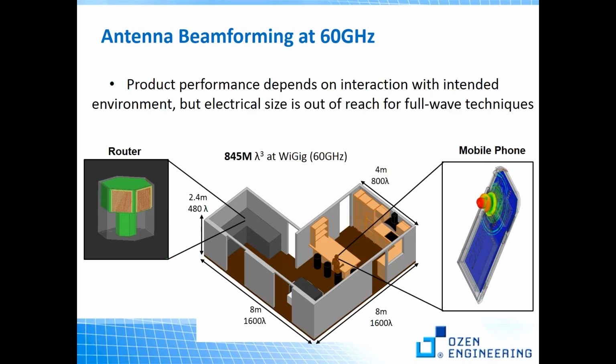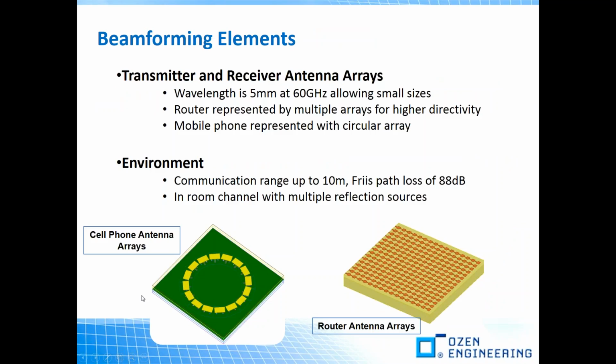So here even ANSYS offers multiple solvers working together to model this whole system, because when you install the antenna on a platform here, it's going to be a multi-scale problem. So you have very large structures compared to the wavelength. So basically electrically large structures.